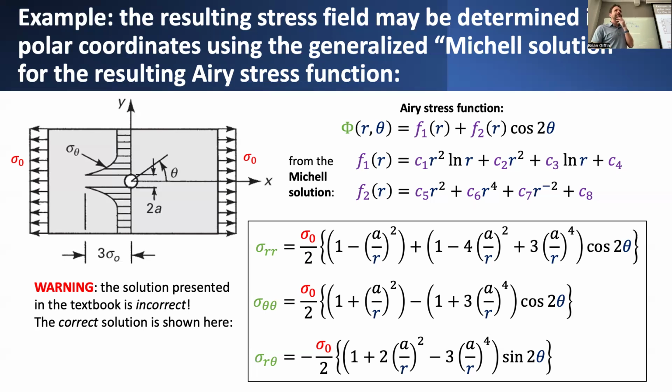So if it wasn't a hole and the geometry was something like a crank. Right, yeah. The way that they typically do this, and I think the book even presents this particular solution, is that instead of considering a circular hole, they treat it as sort of like an ellipse. And then you can consider the special case of what happens when the ellipse has one principal diameter shrink to 0. So it's like you have a straight crack through the medium. And that's how they come up with the solutions, still in polar coordinate form and still assuming the Mitchell solution, which give you these small cracks in an infinite medium. So kind of useful, kind of cool.